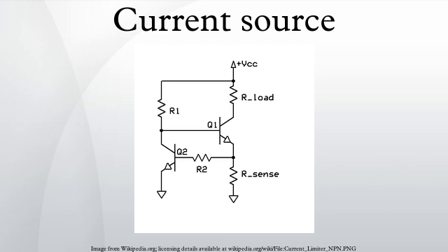Current and voltage source comparison. Most sources of electrical energy are best modeled as voltage sources. Such sources provide constant voltage, which means that as long as the current drawn from the source is within the source's capabilities, its output voltage stays constant. An ideal voltage source provides no energy when it is loaded by an open circuit, but approaches infinite power and current when the load resistance approaches zero. Such a theoretical device would have a 0 ohm output impedance in series with the source. A real-world voltage source has a very low, but non-zero output impedance, often much less than 1 ohm.